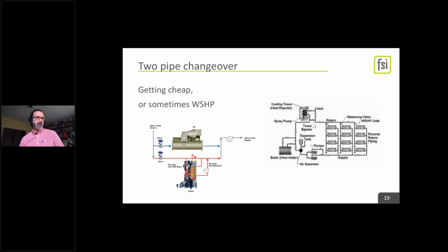So this is an obvious, particularly for the water source heat pump, go into a heat pump chiller on that water source heat pump loop. So instead of a boiler, you've got a water source heat pump. You already were only going to make 90 or 100 degrees, so it's well within capacity. You don't need your cooling tower. You can run the chiller side. You can keep your cooling tower if you want. It's a modest energy win.